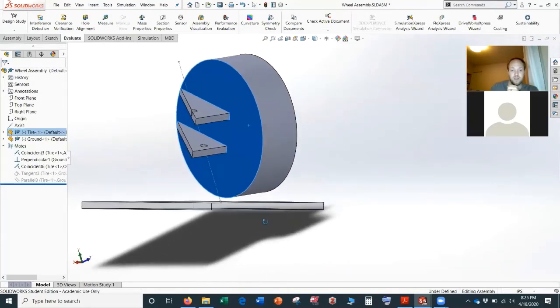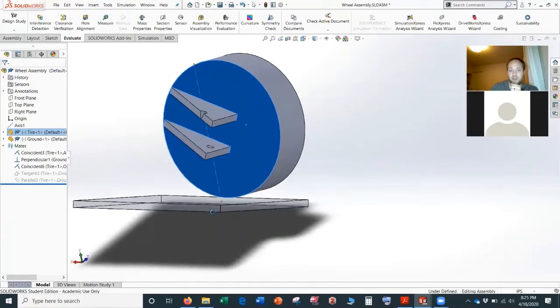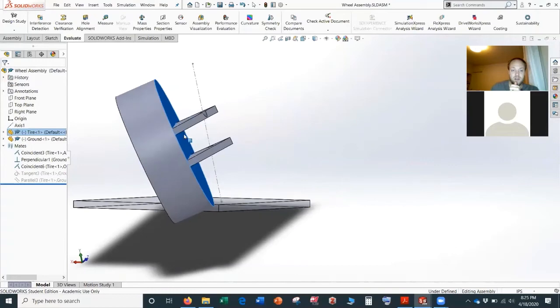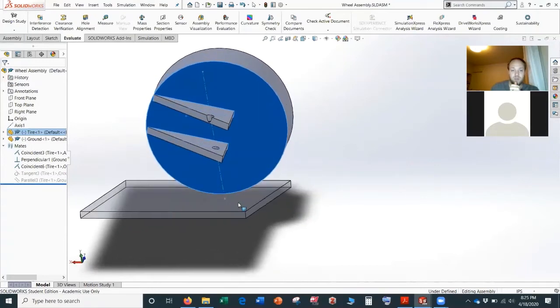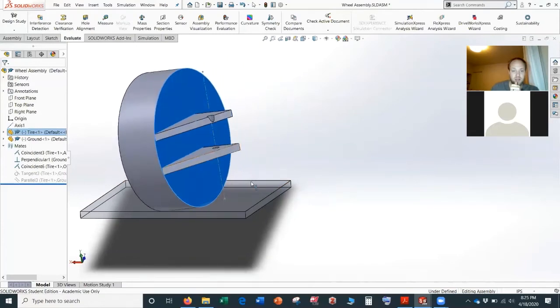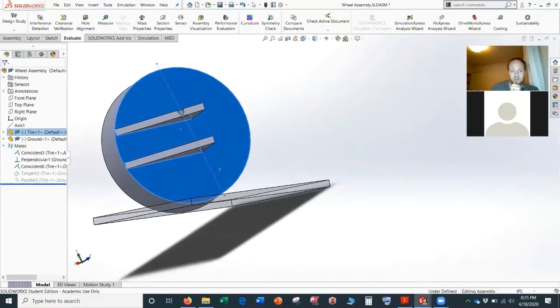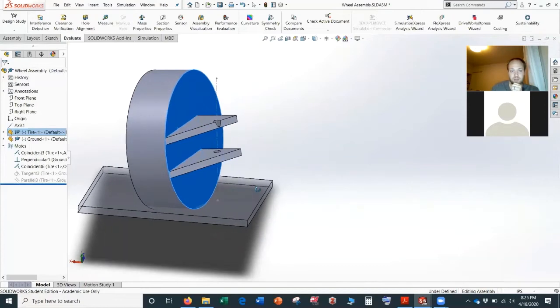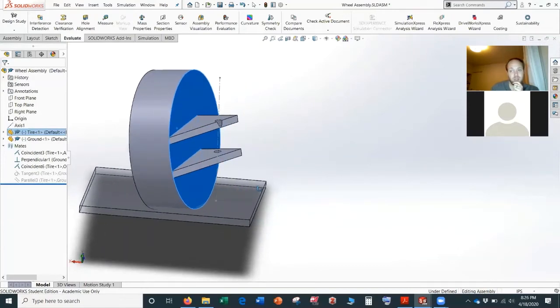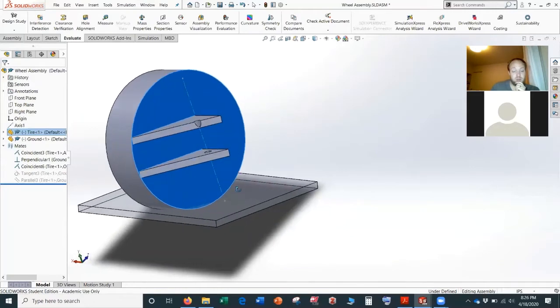And so you can see that, I think just partially because of the parameters I put in, I probably have more caster angle than I do kingpin inclination. And so that showed this effect. I think if we made the caster very small and the kingpin inclination very big, and also messed with the trail and the scrub radius, we could have seen the opposite effect. But this is probably what's going to happen in your car. And this turns back, and as that turns back, it really dips in. So we're seeing something a little bit closer to the case with just caster, which was slightly more advantageous. So that's probably not a terrible thing.